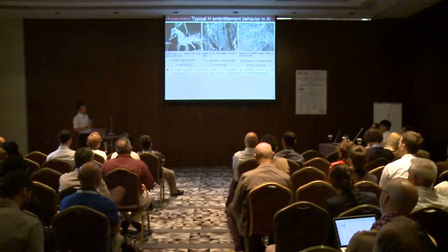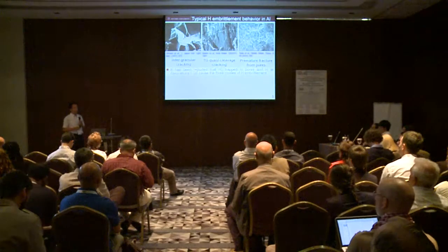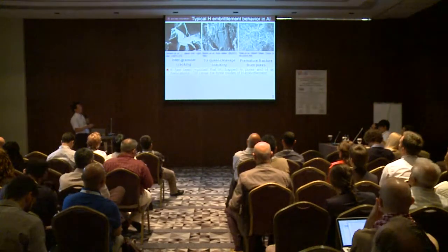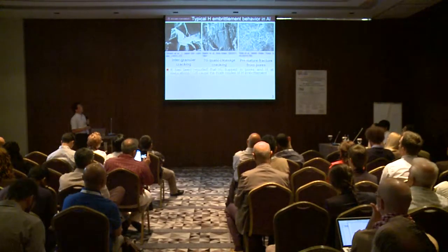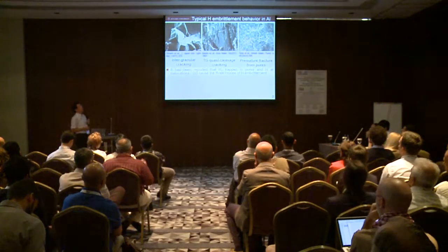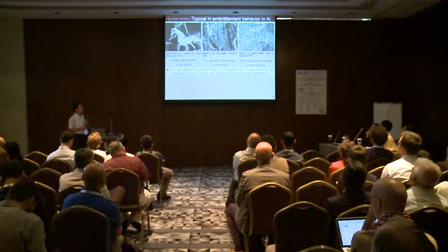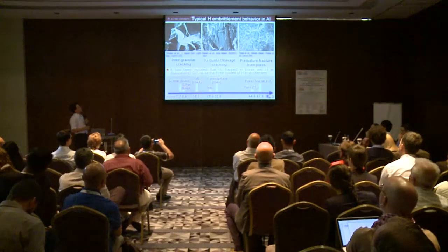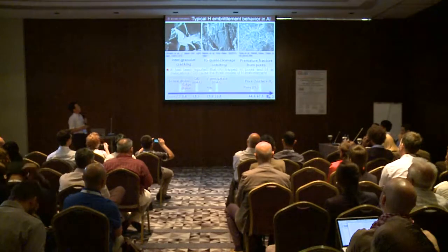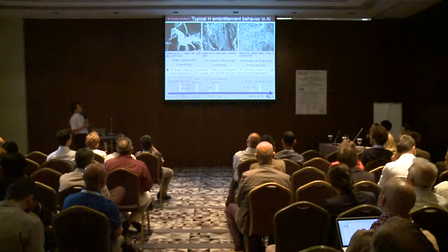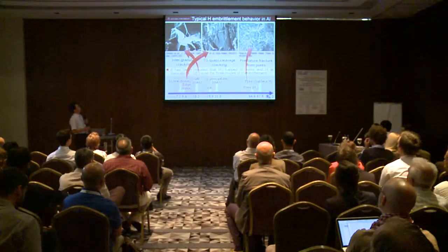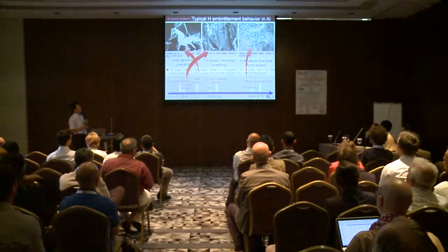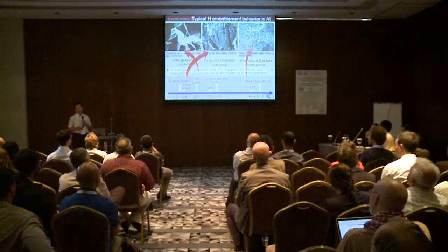By the way, we also observe hydrogen embrittlement in aluminum alloys in the form of intergranular cracking and transgranular quasi-cleavage cracking. More recently, we have confirmed the existence of another type of hydrogen embrittlement, which is the degradation of mechanical properties due to the existence of high-density hydrogen micropores. So we have 3 mechanisms for hydrogen embrittlement of aluminum alloys. But looking at the chart, quasi-cleavage cracking might be associated with dislocations, and intergranular cracking is of course associated with hydrogen at grain boundaries. But as you can see, those 2 trap sites have fairly low binding energies with hydrogen. So at this moment, we can't correlate hydrogen embrittlement with hydrogen trapping in aluminum alloys.